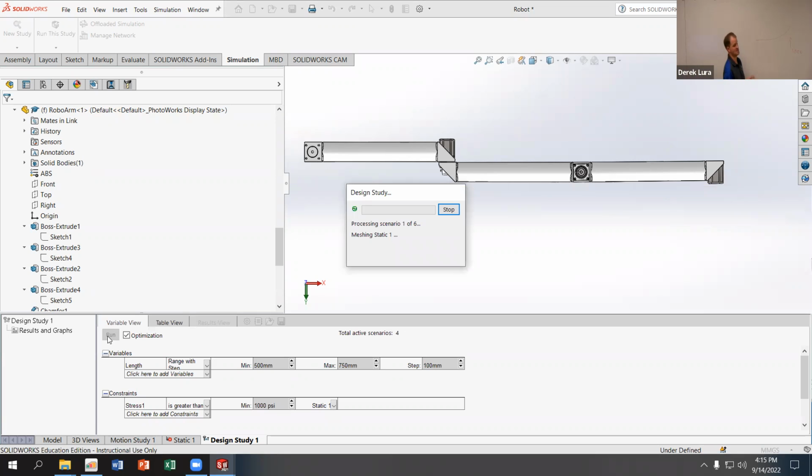It is going to have to run the simulation, the study as you defined for every scenario you've defined. And it'll run additional ones if it doesn't find a convergent solution based off of the initial set. So this can take a very long time to process and get results out of, especially as your assemblies get more complicated, and if you add a lot of additional constraints.